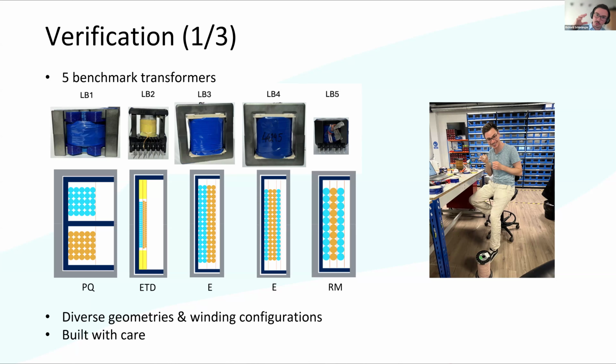You will find that, for example, if you have a window which has 50 millimeters height, the leakage path has to cross that, and then it also has to cross the air gaps, which might be in the region of 0.5 or 1 millimeter. So really, it doesn't change a lot the reluctance path that the leakage field faces. So the impact really is negligible.